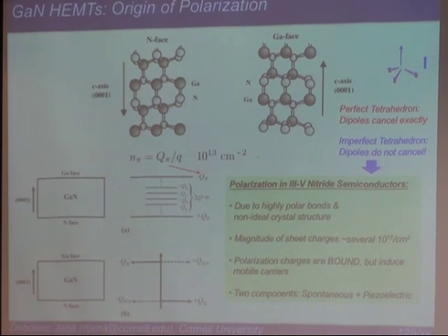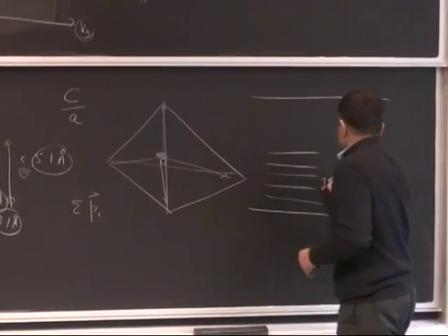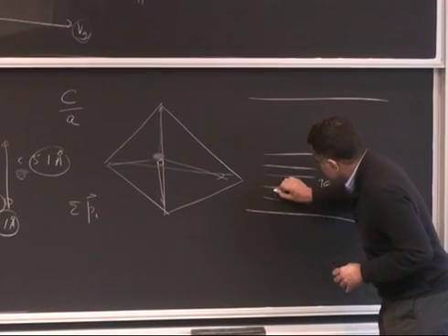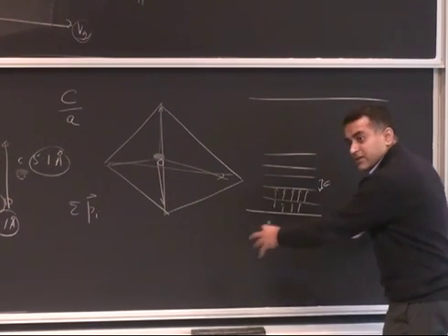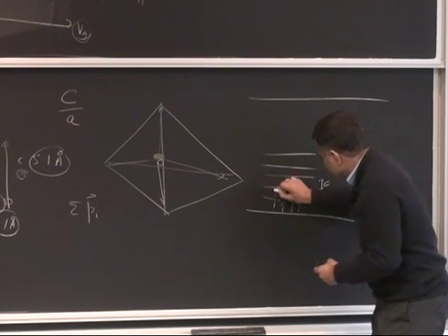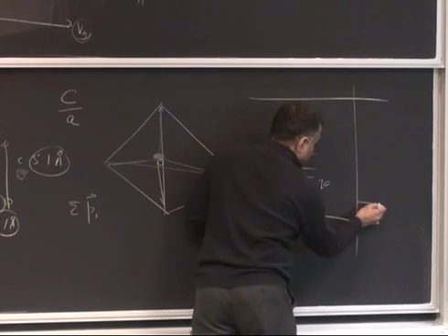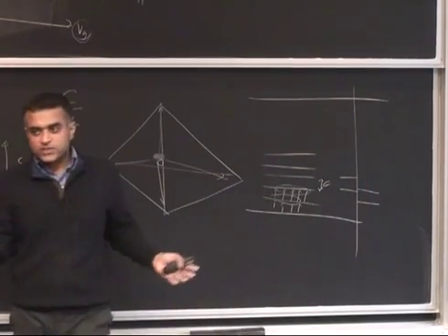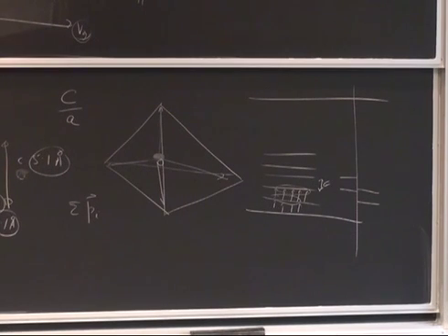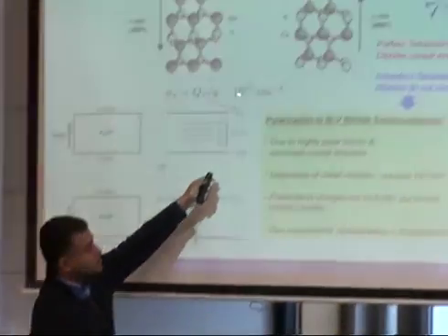It's frozen, and as a result, you can think of this crystal of gallium nitride as many of these unit cells. Every unit cell is distance c, and inside every unit cell, you have these dipoles, right? Like that, and there's another dipole like that, an array of them laterally, right? And you join all the tips and the tails of them, right? What does it look like in terms of charges? Charges look like, well, I have a positive sheet charge here, and a negative sheet charge there, and a positive sheet charge here, and a negative sheet charge. So it's kind of going back and forth, right? You see that sheet charge is repeating, right? And on every plane perpendicular to that c direction. Calculate what that sheet charge is: 10 to the power 13 per centimeter square.